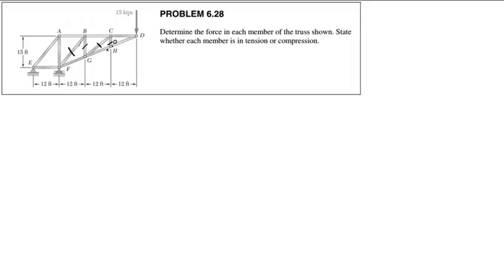Now it may not look like a column because it's kind of on its side, but in structural engineering, anything that's taking compressive load is called a column. So this thing can now take 9 times the load it would otherwise take. Those members can be absolutely essential, even if they're not needed to carry any load themselves, merely for bracing purposes. But anyway, that's beyond the scope of this course.